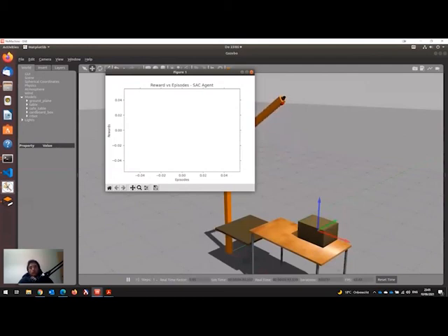The second constraint I came across is the inability of using path planning due to the physics and inertial parameters of the robot model. Since the robot model is too simple, the inertial parameters are based on assumptions and calculated based on the cubic properties of the robotic model. The problem arises in position control, since the box is always thrown when the robot comes in contact with the box, which is not very good.